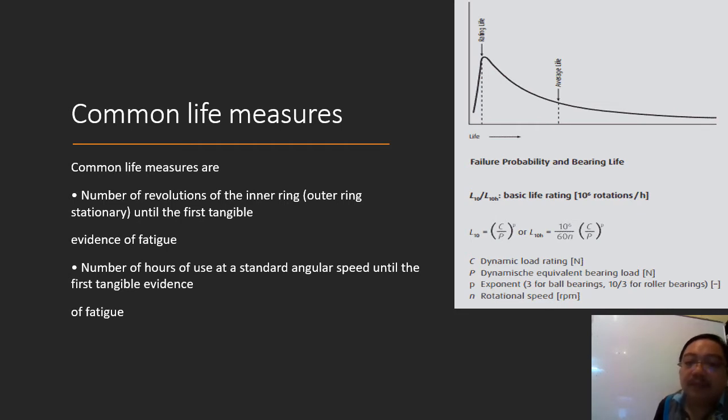Sometimes you may also see physically that the bearing itself has changed color because of the heat affected zone and fatigue failure of the shaft.